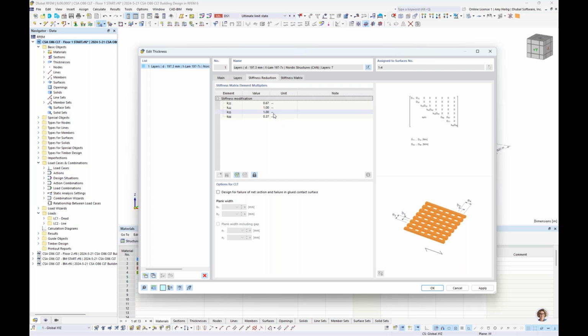Well, RFEM is actually utilizing what we call the laminate theory, and it's going to directly calculate the shear stiffness matrix entry D44 and D55 directly, considering both shear and bending deformation. So the laminate theory is certainly a more detailed and exact approach when we compare it to the analytical equations from the shear analogy method. But point being that that reduction is all taking place underneath the hood with the laminate theory calculations, so we likely are not going to adjust these factors.